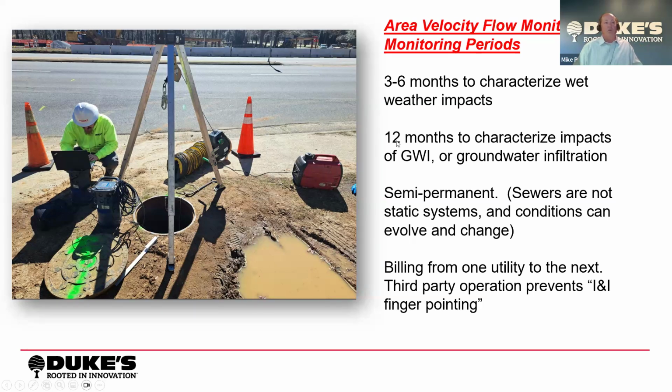Sometimes they're 12-month studies where the general idea is that we also want to see the groundwater infiltration, which will show up during dry weather at one part of the year versus dry weather at another part of the year. So the flows could be very different, and generally those are tied to groundwater infiltration values.